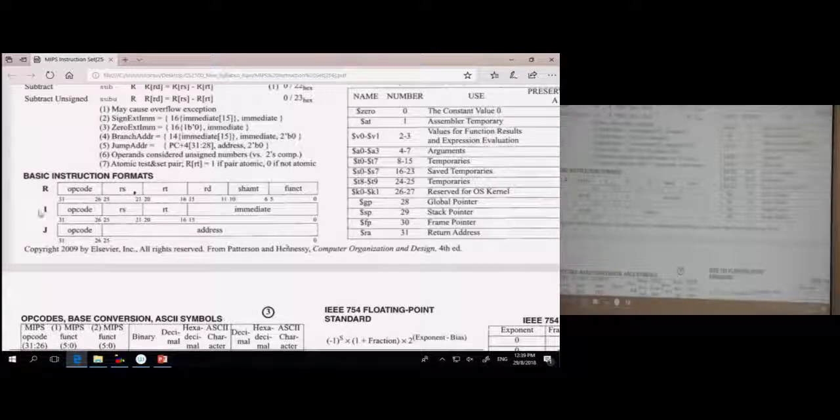The other type of instruction that we look at is the one with the immediate value. You have 1 register, add or subtract or whatever with the immediate value and store into the final register here. So currently we have looked at 2 different types of instruction, R instruction and I instruction. R instruction is 3 registers, 2 source, 1 destination.